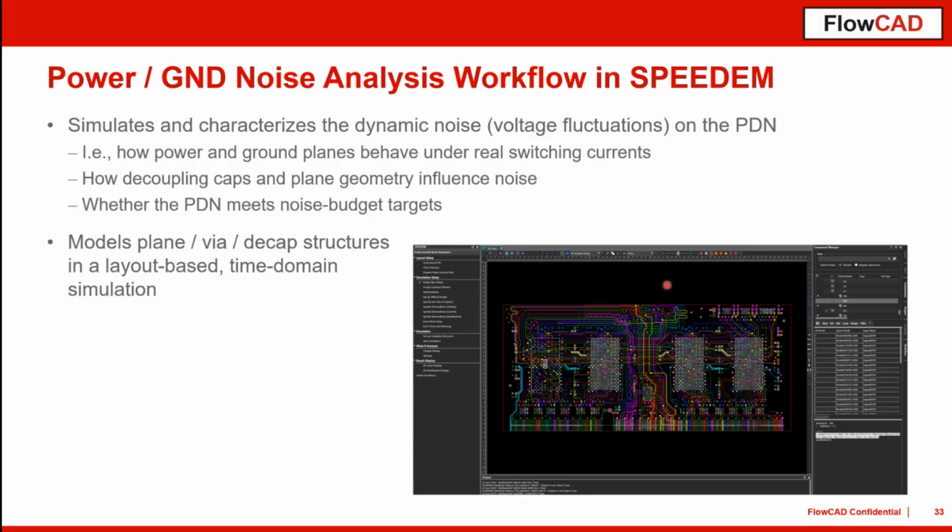That means how the power and ground planes behave under real switching currents, how decoupling capacitors work, and how the plane geometry influences the noise. It also models the planes, vias, and decoupling capacitors or structures in your design. The setup is similar to the previous power-aware setup, and therefore I don't want to go into more details here.